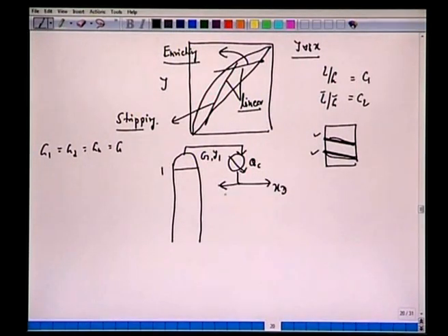Now we have this condenser Qc, where the vapor condenses totally to give rise to this XD, and we have this reflux X0 with the flow rate L. Again, here we are not writing any subscript for L, L0, L1, L2, L3, etc., for the same reason that the molar flow rate of the liquid in this section is also constant as L. So this reflux goes back to the distillation column.